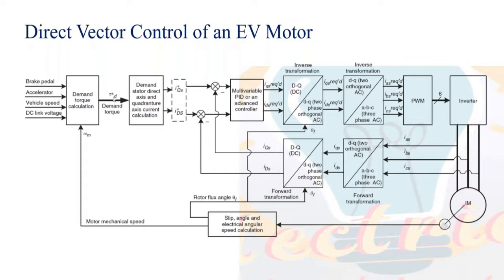So you know the torque-speed characteristic of a motor, correct? From the torque-speed characteristic of the motor, I know where the efficiency of the motor is very high. At the same time, I will also know what the current is at that point. So basically, I generate the reference currents, some reference current based on this controller value. Now I have to consider whether the reference current calculated by the controller and the current which is already supplied to the motor are matching or not.